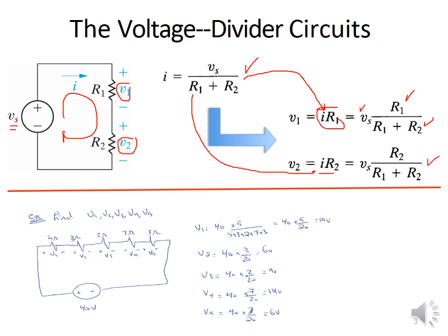من هون هطلب منك تحفظ rule related للvoltage divider circuit. لو في عندي series combination of resistors وطلبنا منك تحسب V1 أو V2 أو يمكن V3 across a third resistor R3 هنقول ال V across a certain resistor هيساوي Vs أو ال overall voltage across this branch which is V supply ضرب ال resistance اللي نحن عم نحسب عنده ال voltage يبقى ضرب R1 لو أنا عم بحسب V1 divided by the sum of all resistors الموجودين بالبرانش يبقى divided by R1 plus R2.